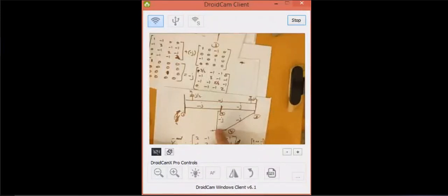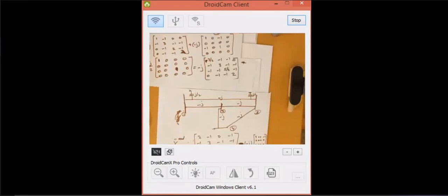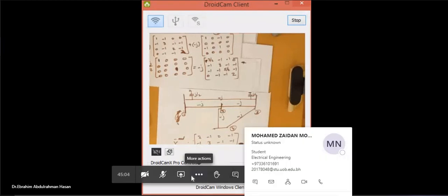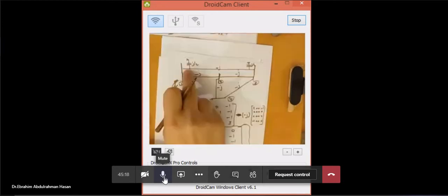This is just a check, but you don't need to do this. Always work with Y modify. How to find Y modify? Okay. Anything we added to the bus, not to the whole line, is as if we put half here and half here. So this one is only connected to bus number 1, and this part is only connected to bus number 3.